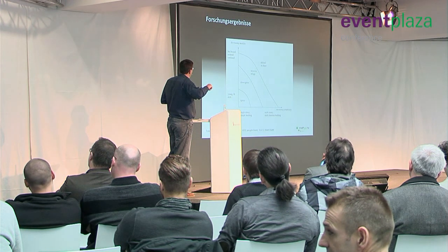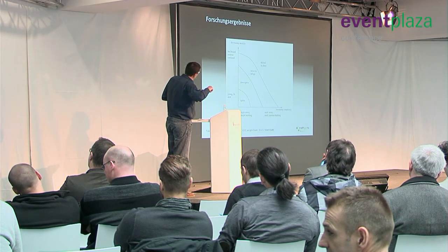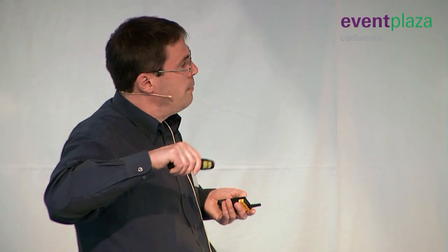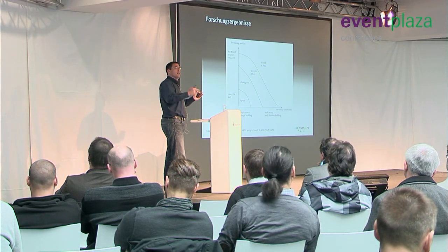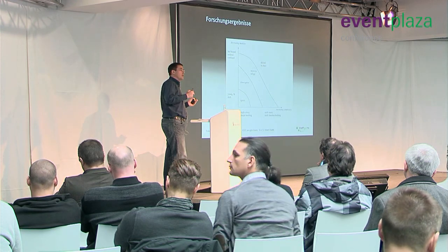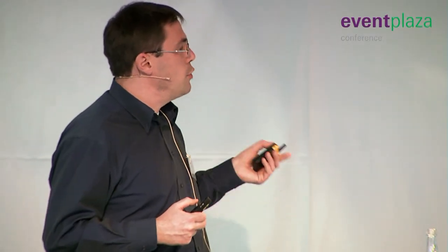We call that egress now, that is the standard evacuation. Very often we are dealing with that kind of situation. In that lower part, you also have to account for complex situations, but we usually assume that they have proper illumination and proper signage. Sometimes you can make it more complicated, more complex and more inconvenient, and then you'll arrive at different results. And you have to assume that the routes are not blocked and that people can understand the announcements being made and all that.